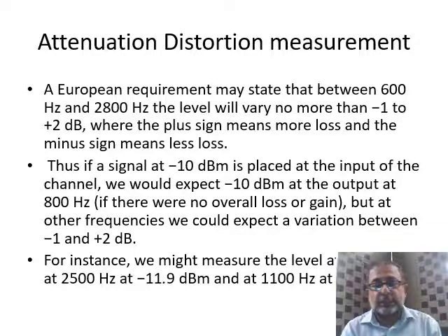We are not talking about the same 800 Hertz at which we were expecting -10 dBm at the other end. We are measuring the attenuation at other frequencies.